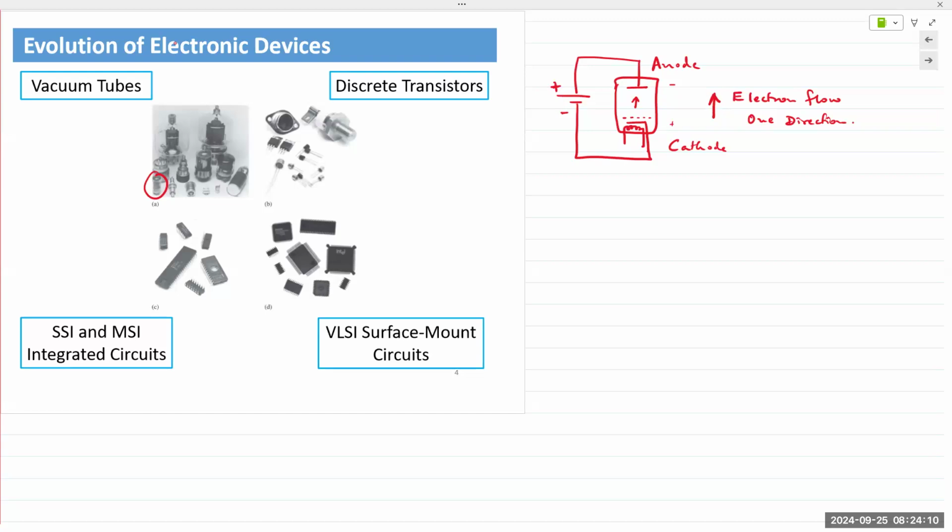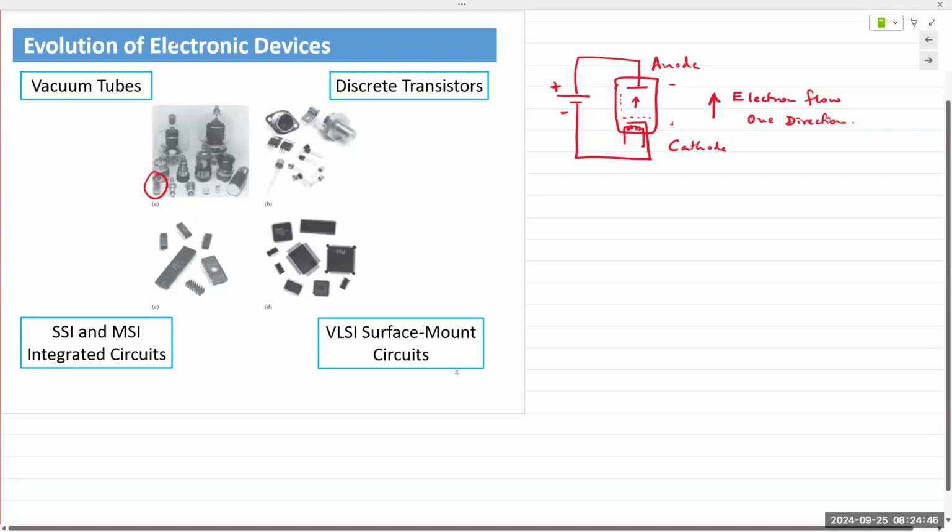So you have a vacuum tube element. You have two electrodes inside it. When you heat the filament, you have a lot of free electrons available for conduction, and you apply an external energy source. The electrons are attracted, and you have current flow through that device. Now, a very basic diode like this would have large variations. You could not control the flow very well just between the anode and the cathode. And so they inserted another electrode on the side, somewhere here, to actually control the flow of the electrons in a better manner.